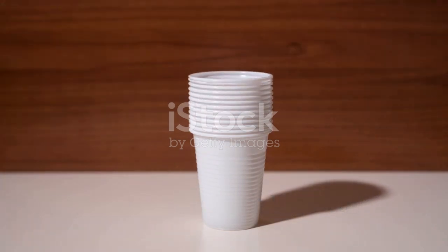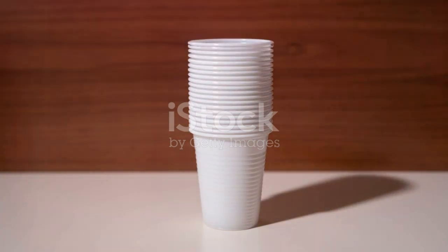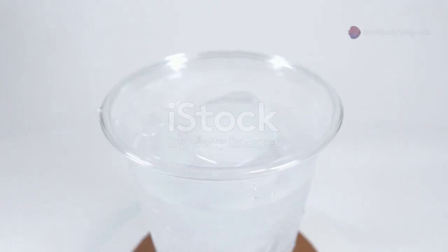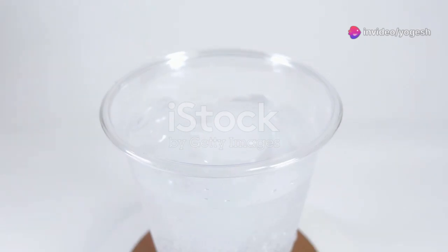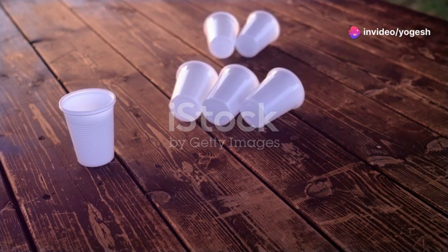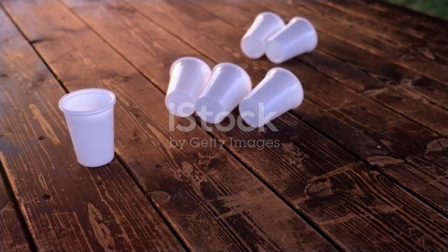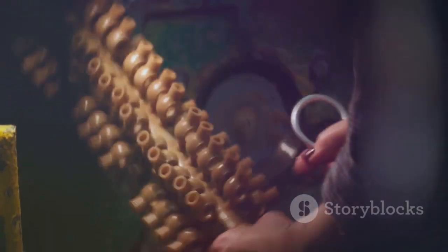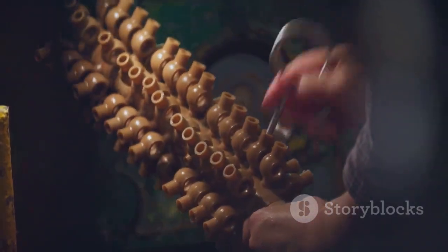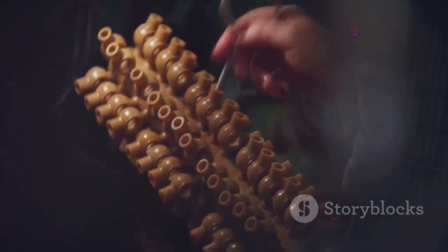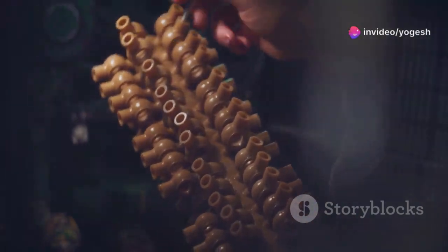Ever notice how plastic cups stack and unstack so easily? That's the draft angle at work. The slight taper that lets them slide apart with no effort. If the walls were perfectly straight, they'd stick, screech, and even break. In factories, zero draft parts are hard to eject, leading to bent rims, drag marks, and ruined products.